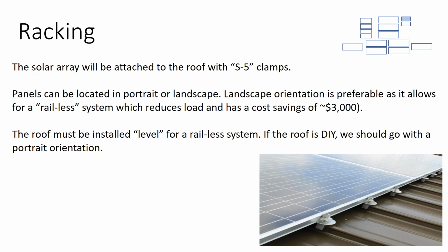I thought going with railless racking was going to save us a ton of money, that it would reduce our racking costs by half or more. But these attachments cost money as well. Instead of going 4 foot on center, we're buying 4 times as many attachments as we normally do, and these attachments are $10 a piece.